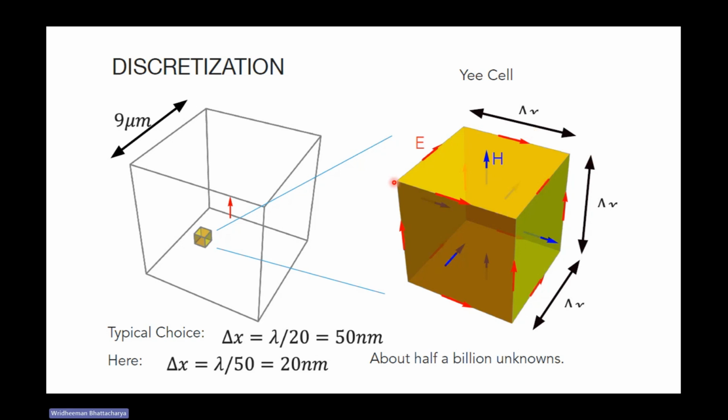So del x in the mesh cell, when we do it in the solver, we have to give the del x size. The del x size should generally be the wavelength which we are shining, divided by 20 or by 10, right? But here, as the structure is too small, we divide it by 50 to get it finer, and the study of the smaller nanostructure would be more stressed upon.